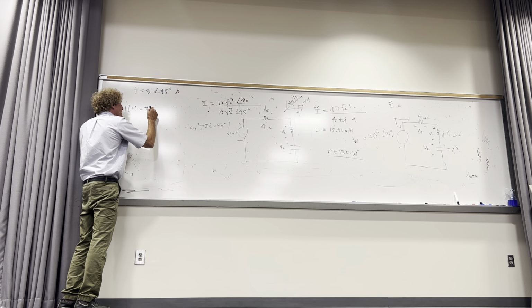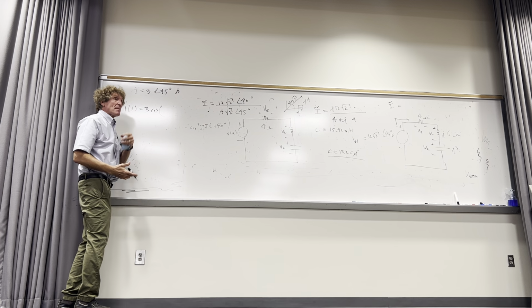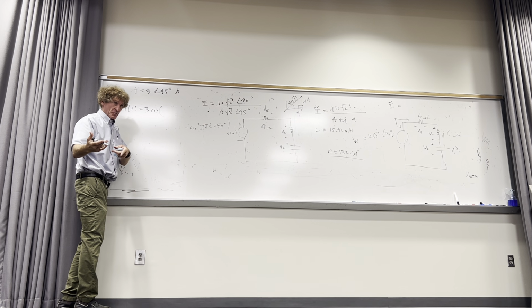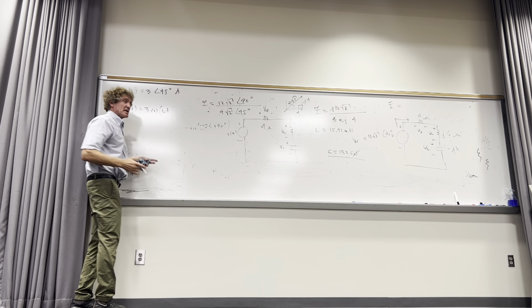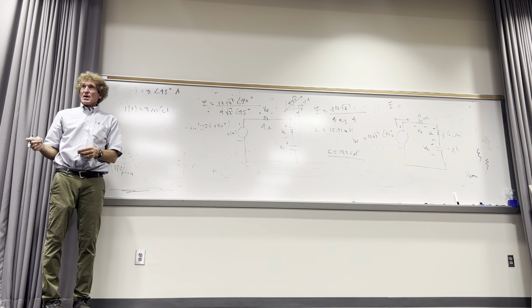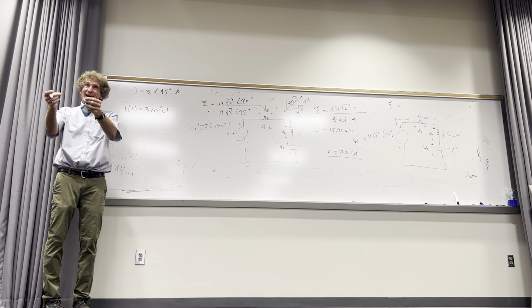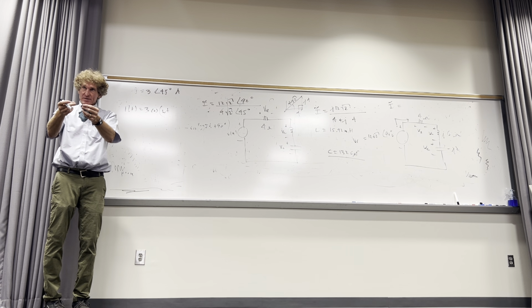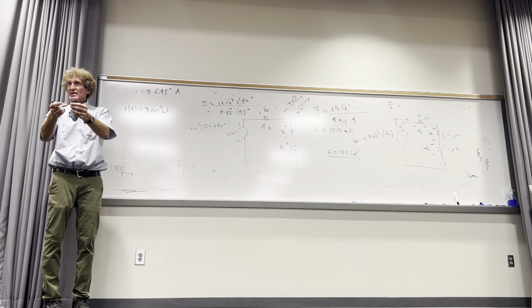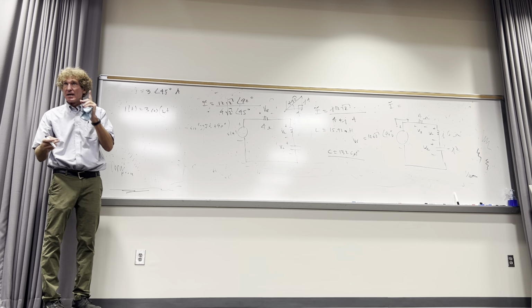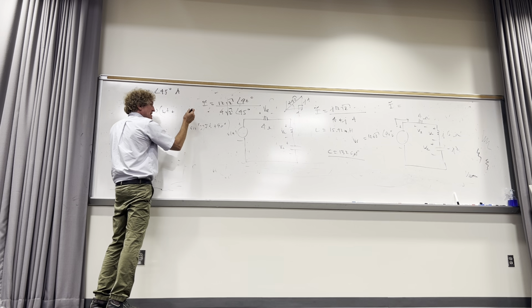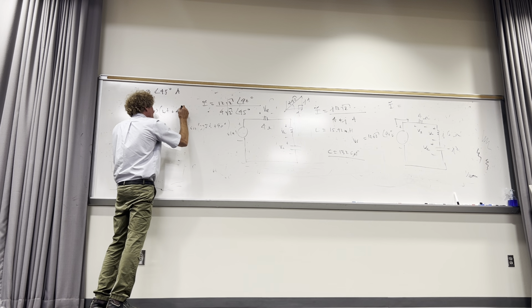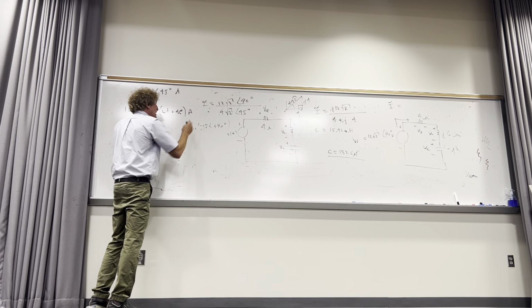Then it will be the cosine of omega t. Omega is 377 for this one. I can put down omega, I'm just putting it as omega t so you get the idea. That is something you have to observe from the actual voltage waveform that's causing this. You all with me? 377 for us. Now the angle is 45 degrees, so you would add 45 degrees here and that would be amps. That would be in the time domain.